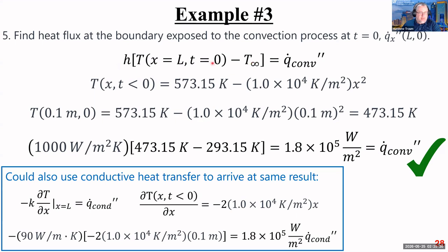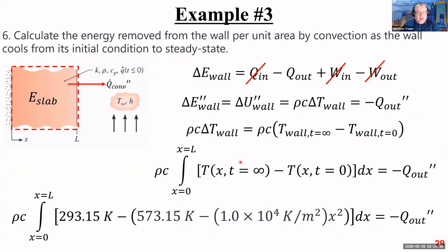So in the previous step, on purpose, the wall temperature is hotter than the ambient temperature. This term comes first, and the ambient temperature is second, to make sure that this term is positive, at least in this calculation, and it should be positive here as well. And then it gets negated. It turns into a negative sign when I account for its directionality in solving the first law of thermodynamics.